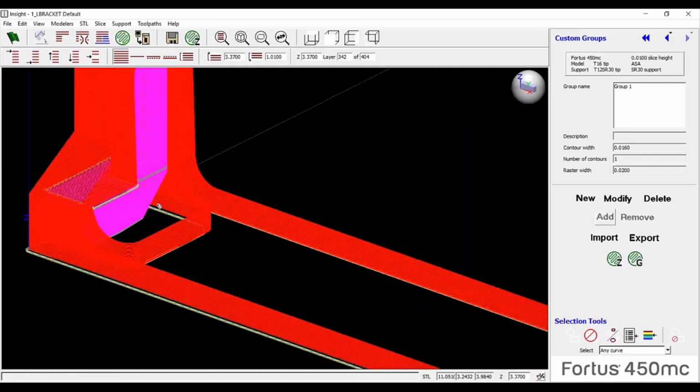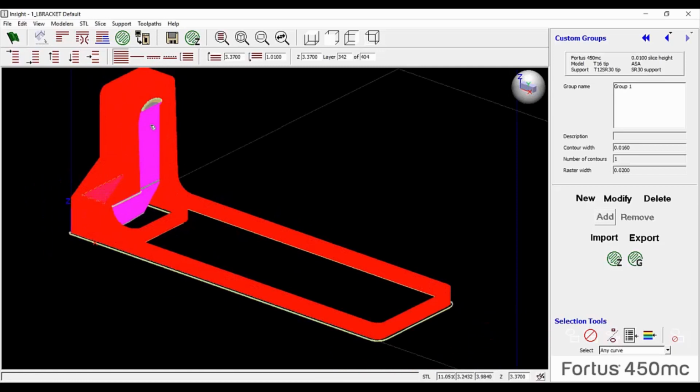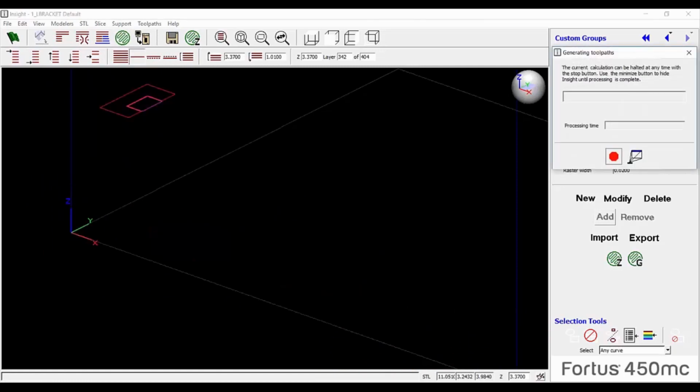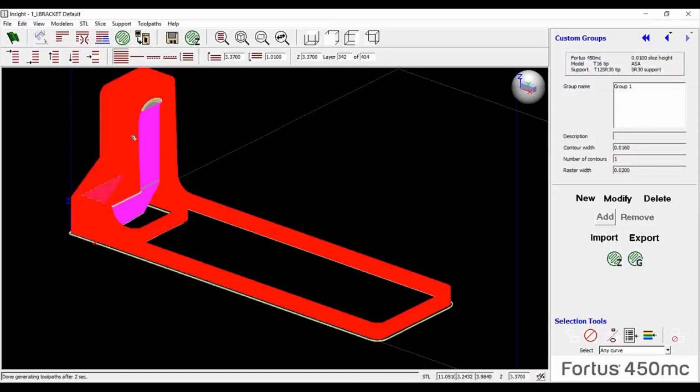So looking at the whole part, all I've done is taken these select layers where the gray has gone to the magenta, and I essentially grabbed the parameters and applied it. At the end of the whole process, we're going to have the exact same part. The only difference is what material is being extruded for the support structure and how many purgings we did.